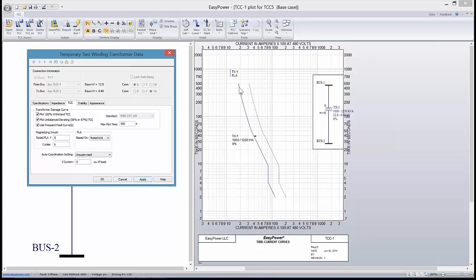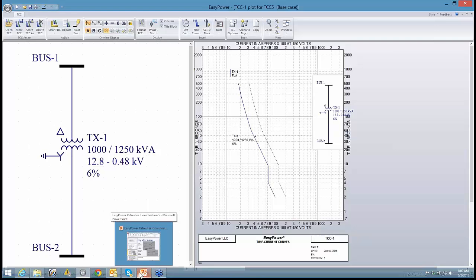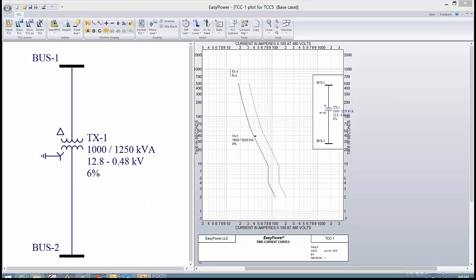And as we apply that, you see the curve now is plotting a different plot, which is 58% below the levels that were indicated for the 100% load current. Again, that's a special case condition, and it's specifically for single line to ground on the secondary, anticipating the damage or the current that's going to be flowing in the primary side of a delta Y. All right.